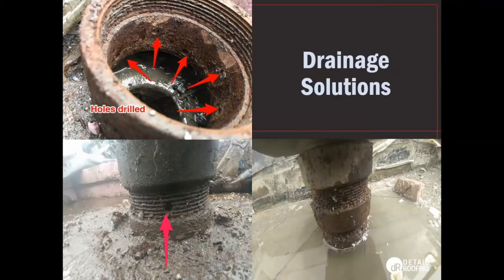An option here would be to drill a hole or a couple holes into the drain, just to help encourage adequate drainage if there is a lot of heavy rainfall or a lot of water built up on the balcony surface. In cases like this, it would still be essential to make sure that the drains are cleared and unblocked, because if any debris did get inside of the drain, it still could slow down the drainage, but this can be very helpful for any heavy rain buildup.